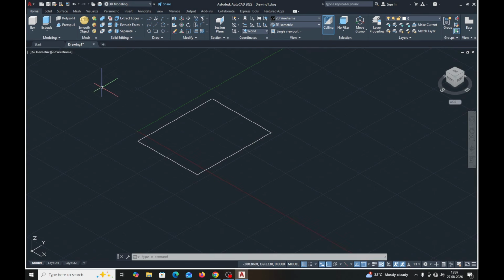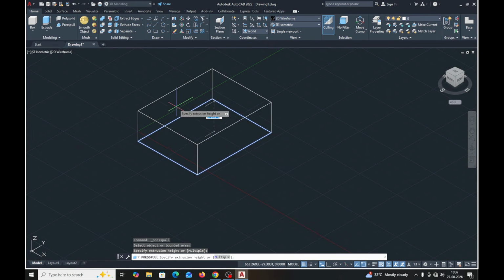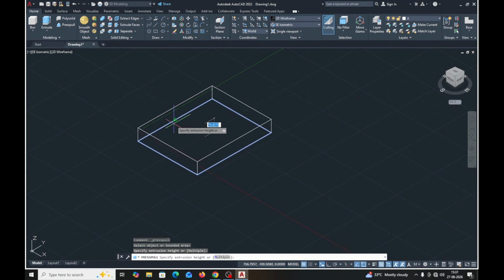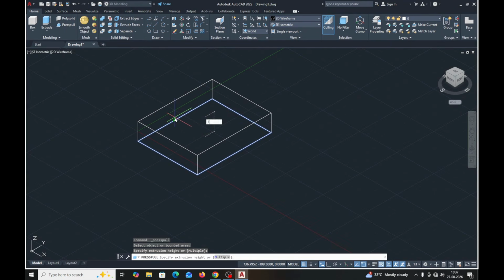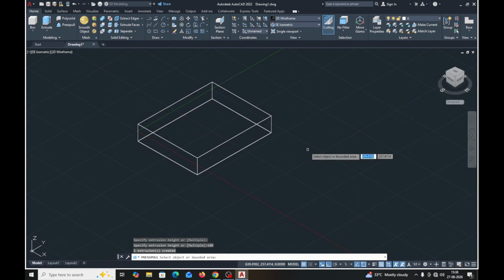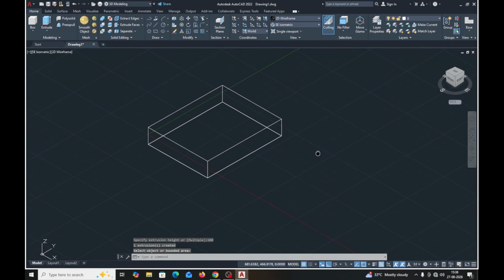Now the press pull command. This is the required geometry. Select press pull. Bring your cursor inside this boundary, it highlights, click, and move up and down. Give a suitable height, suppose 100 mm. Enter. The press pull command is still active, so escape out of the command.